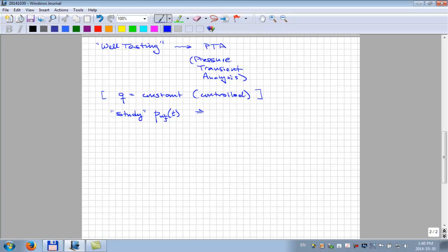And from that study we're able to estimate permeability primarily. That's the most important number you're looking for. Possibly this skin factor we talked quite a bit about last Thursday, the magnitude of that, if it was 2 or 8. Remember what 8 was? 8 was an important number because you're now producing half the rate as if you didn't have skin.